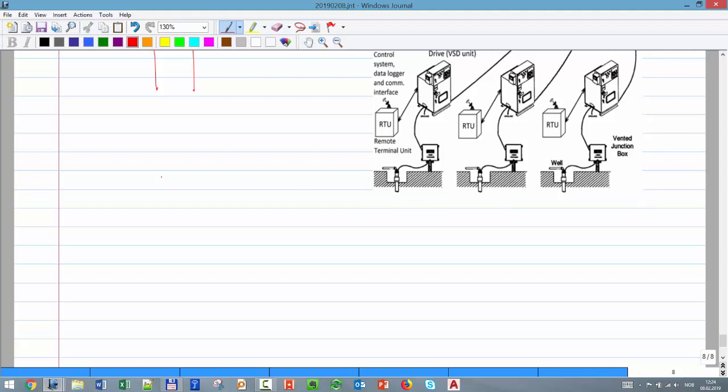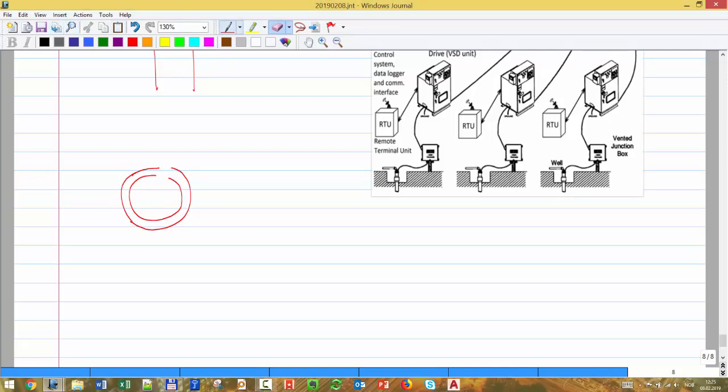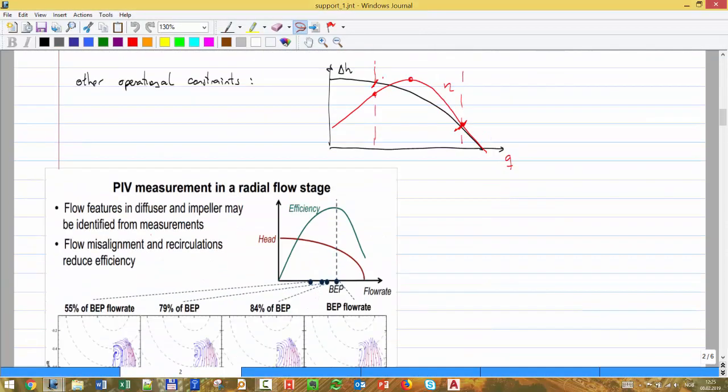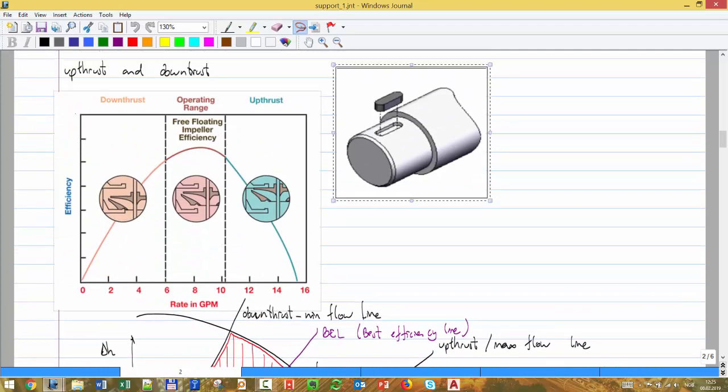So you have the axis, which looks like that, and you have this rotor, which looks like that. But then to connect them, because one is rotating and this one also has to rotate, you need a mechanism which is called a key. You make a groove here, you make a groove here, and you put a piece of metal in between to hold it. That's what we call a key. I think I have a better one, a key, something like that.